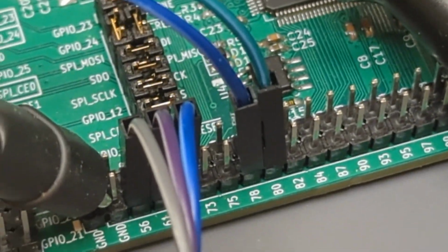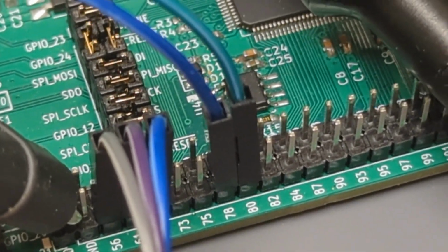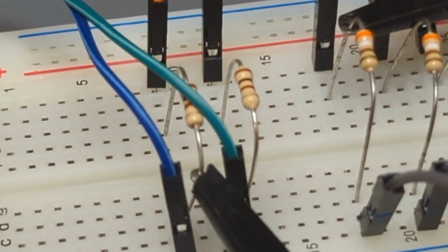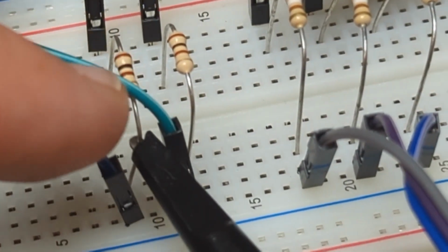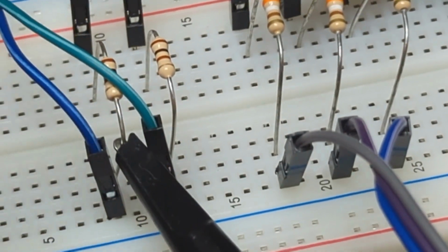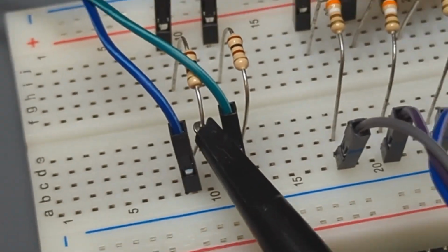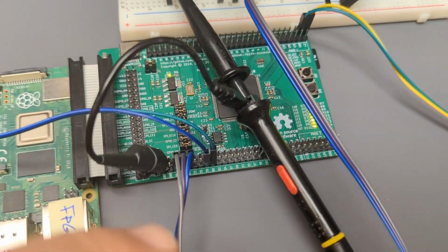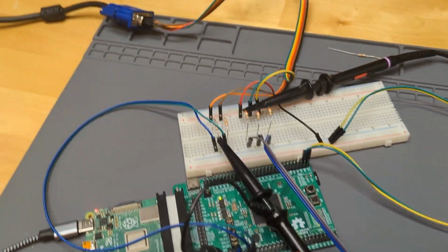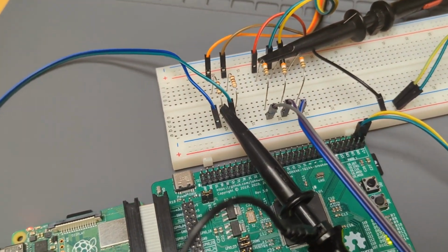As you can see, the blue wire on this comes out on number 79. We'll go back to the PCF file and verify that that is, in fact, the horizontal sync as it goes through these resistors there. By the way, I can see in this shot those are 100 ohm series resistors for the sync signals. I put 100 ohm in series with these pins just because the FPGA has a very high slew rate on the signals coming out of here, and these wires are antennas and long cables, bouncing all over the place, and they're going to get noisy, with a lot of overshoot and ringing.